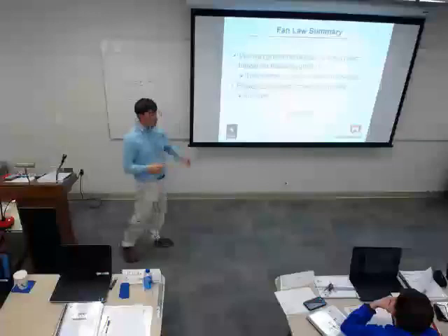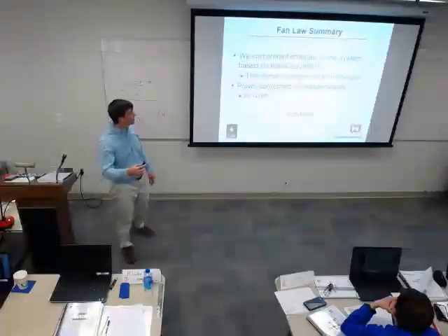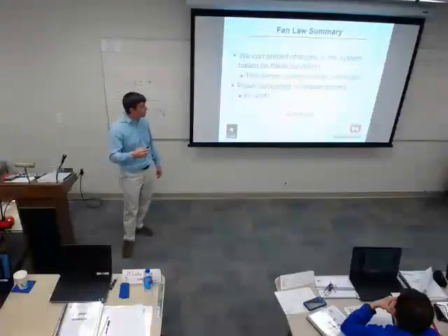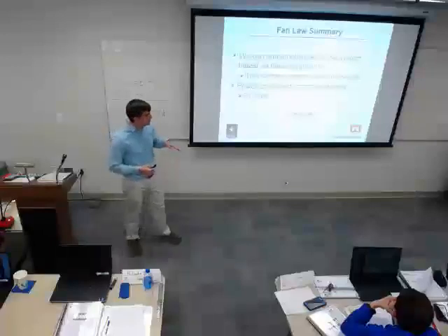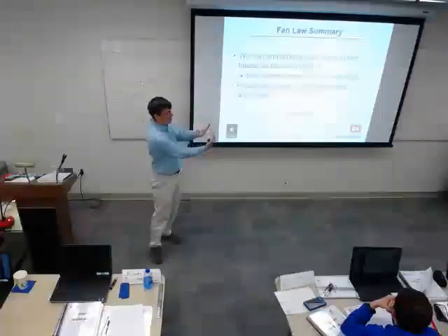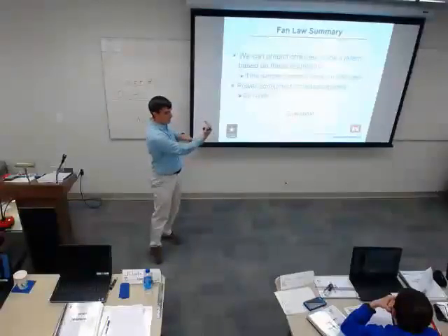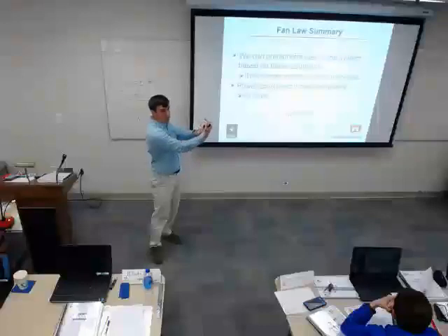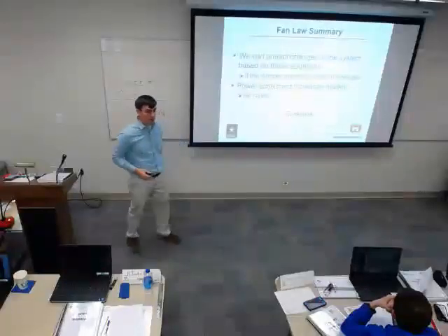All right, summarizing all that, we can predict changes in the system based on these equations. I showed you the system curve. I had my fan curve going this way, my system curve going this way. I'm going to change the revolutions per minute that my fan is operating at, and ride up and down that system curve.